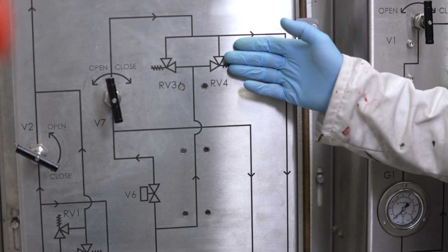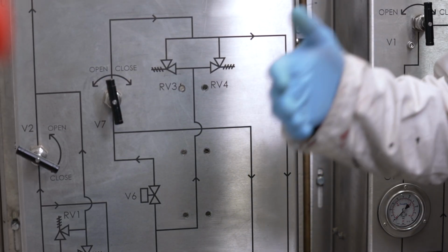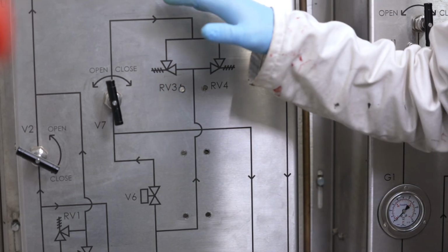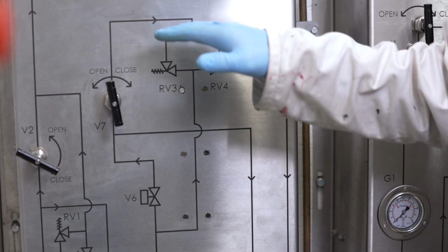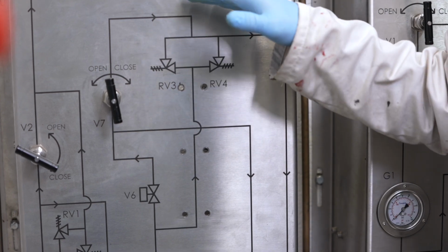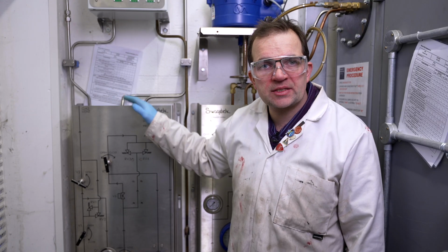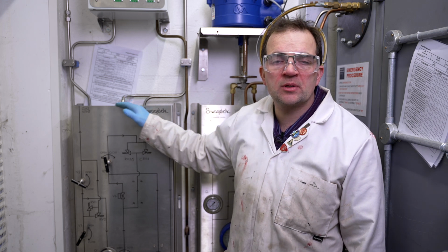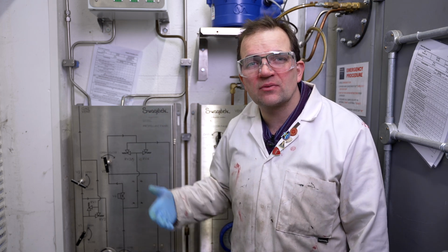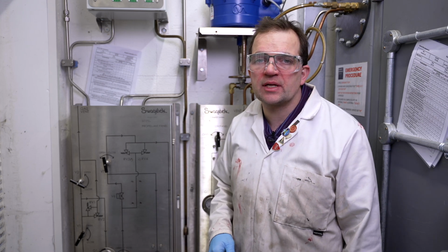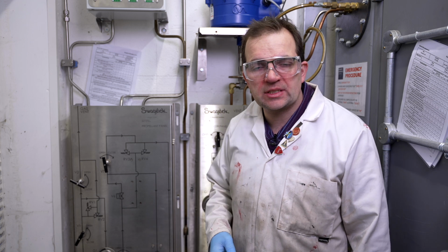So when putting a pressure panel together like this, you need to think about some of the basics first. Where is the panel actually going to be mounted? Have you done all the correct paperwork? If you're unsure of the regulations that you need to conform to, then look at the PSSR regulations, and specifically for pressure assembly equipment which is in permanent use, you also need to think about things like the written scheme of examinations. Okay, please consult with your local health and safety manager or the HSE for more details on that.